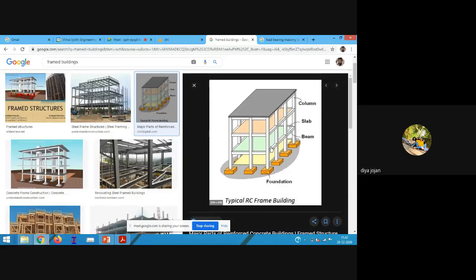Yes, sir. This is actually the basic frame of a building, and you might notice while passing through some areas where these types of buildings are being constructed. First we construct this basic structure, and once the structural part is completed, we start to construct walls. Since walls are no longer taking any loads, there is no need to construct them using bricks.